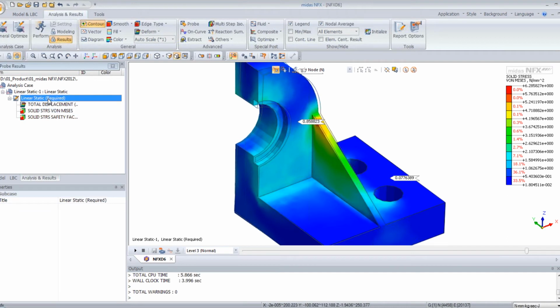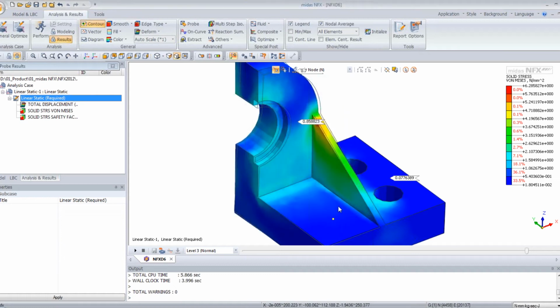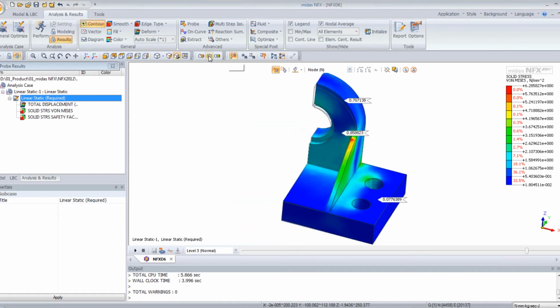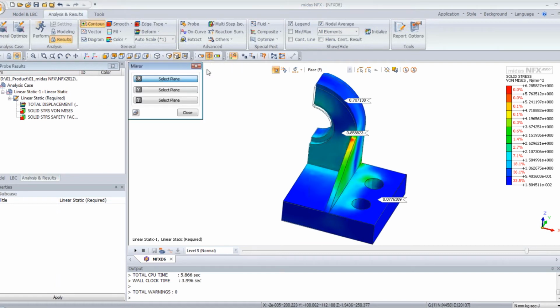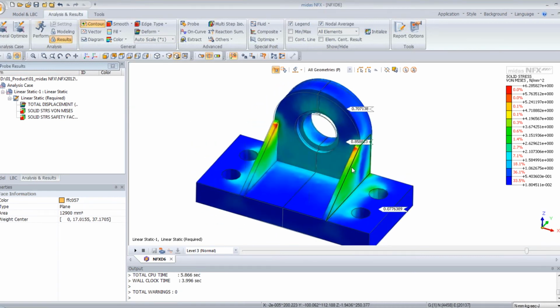And if you want, it's possible to add a lot of types of loads. You have these 3 types basically, but you have a lot of other types you can add. And as it is a dummy model, you have the symmetry mirror plane here. So by clicking here and selecting your plane, you will be able to view your complete model.